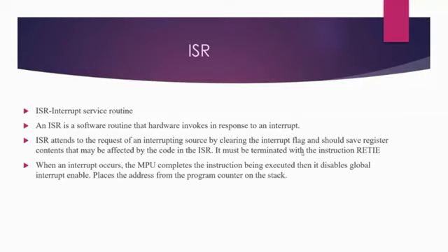ISR. ISR stands for Interrupt Service Routine. An ISR is a software routine that hardware invokes in response to an interrupt. ISR attends to the request of an interrupting source by clearing the interrupt flag and should save register contents that may be affected by the code in the ISR. When an interrupt occurs, the MPU completes the instruction being executed, then it disables global interrupt enable, and places the address from the program counter on the stack.